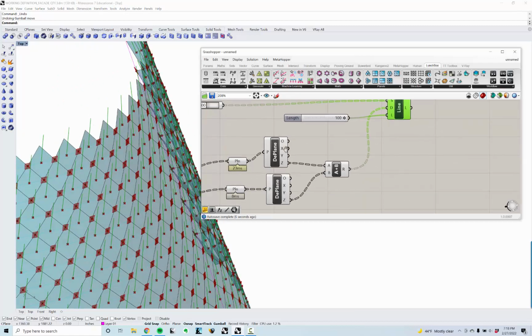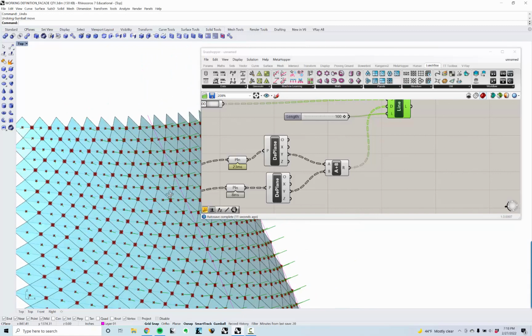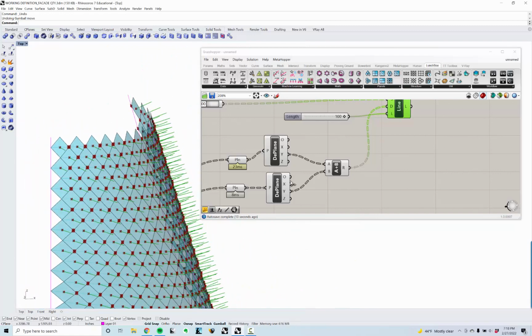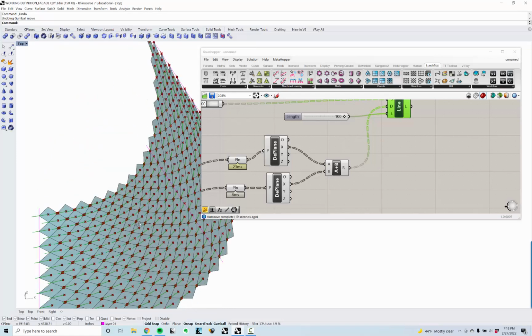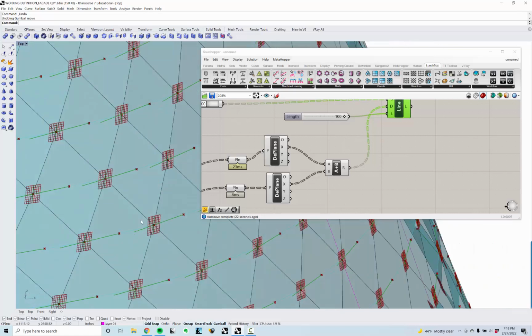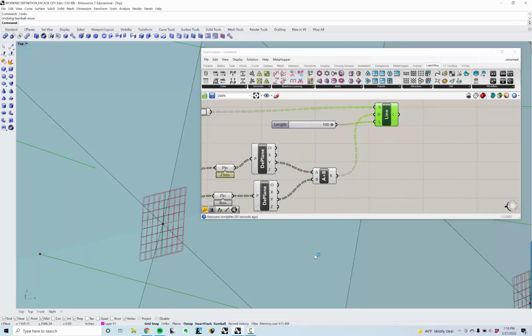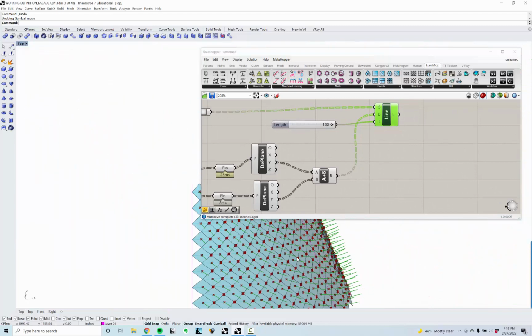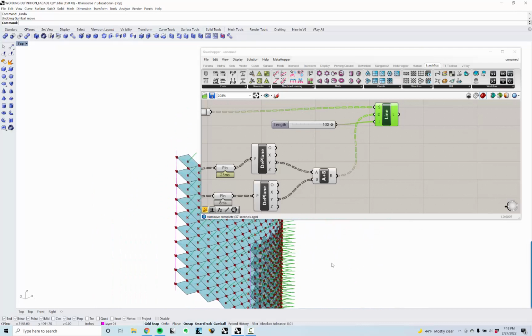I'm going to try to just use the Y's, see if that works. Yeah, that's working. It might just be something with how the plane is twisted, that the vectors that it's using are not oriented normally, but it seems like if I use the Y's it works. Sometimes the planes, depending on how the surfaces are being built, get a little bit twisted, and if you use a different vector it'll help.